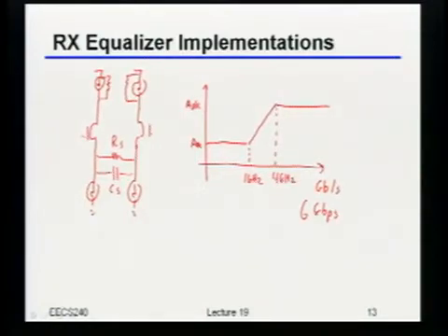Okay, so where did 4 gigahertz come from? 2/3 of the bandwidth. But now I want to push you a little bit. This amplifier I drew has infinite bandwidth, right? Because I didn't add any caps at the output. The only reason I have this pole is that at some point, when that cap kicks in, I can't do anything better than shorting the two tails together. At that point, I've already gotten the full GM from these transistors.